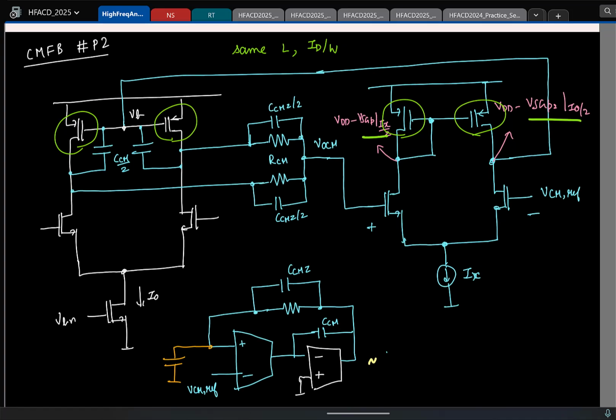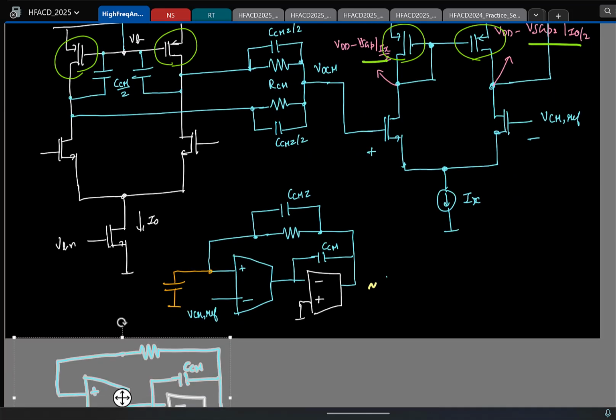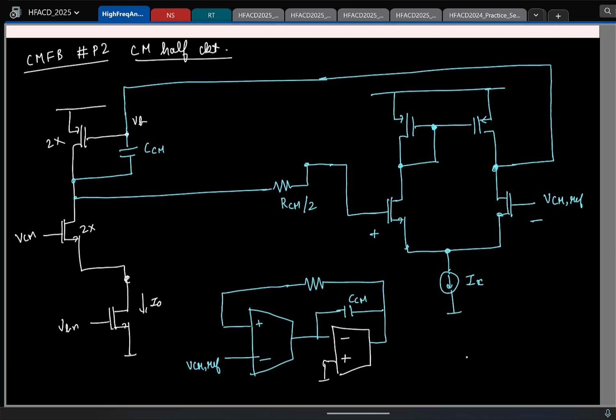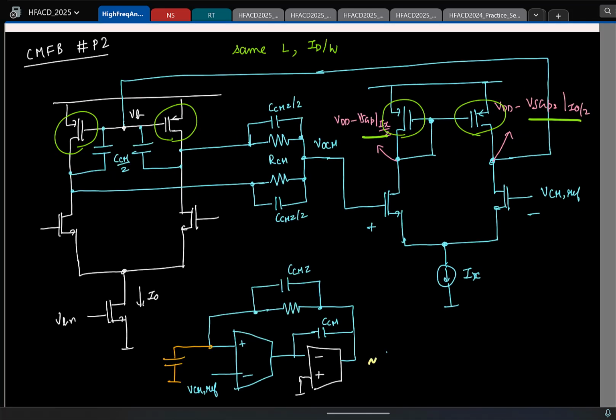So cool. So now we have seen what happens with the common mode picture, and we saw that for common mode signals we need to stabilize it and take care of the sizing properly. Then the output common mode will hopefully be set to the applied VCM ref. Common mode is fine. But again, let's not deviate ourselves. Our main job is to make a differential amplifier. So let's actually see what is happening to the differential mode gain. I'll just again take this.